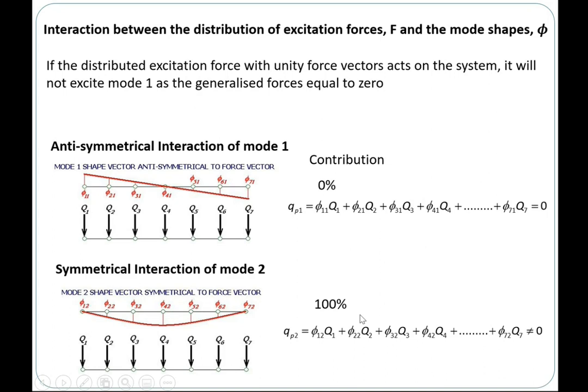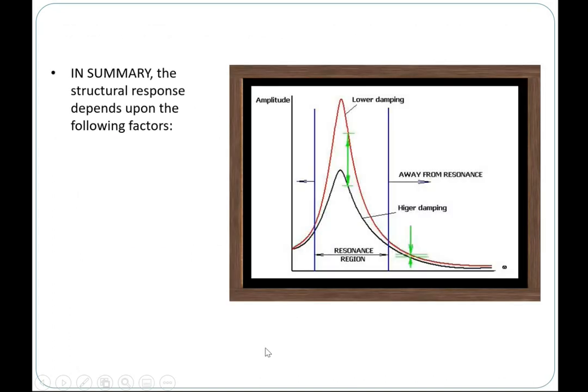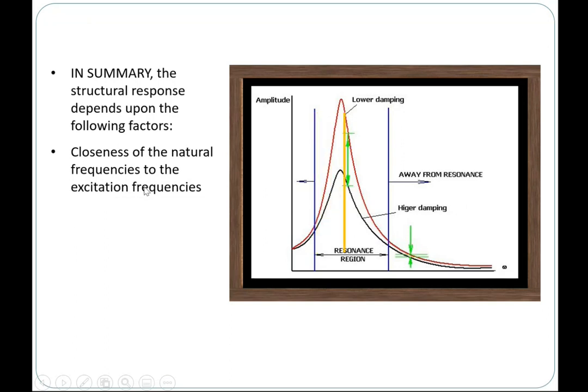So here we want to say that we don't talk about how high the force is. Assuming the force is very small, when the excitation frequency is close to your natural frequencies, you have low resistance, high vibration, or resonant conditions.